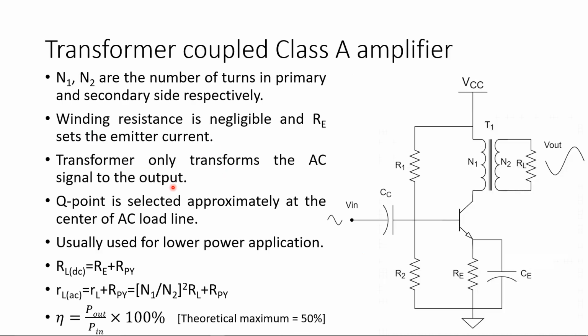What we have done here is just consider the base current to be very small, so that it will rarely impact the emitter current. To ease the calculation, we are assuming that the emitter current is equal to the collector current. Basically the actual equation is that the emitter current is equal to the base current plus the collector current, but as the base current is very small, we will consider the emitter current and the collector current to be the same.